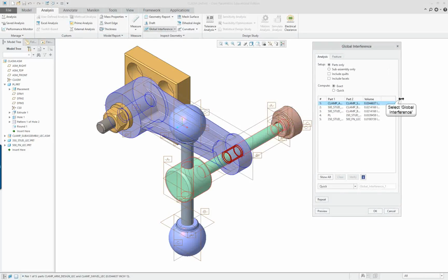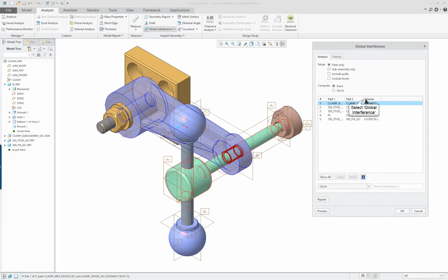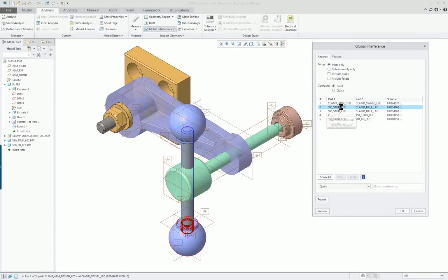It's going to preview the places where it interferes between parts. And it's going to interfere, obviously, every place where there's a threaded surface, because the hole is smaller than the shaft in every case. So you're going to see each one of these has the threaded area as an interference, which is what you want, of course. Like so.